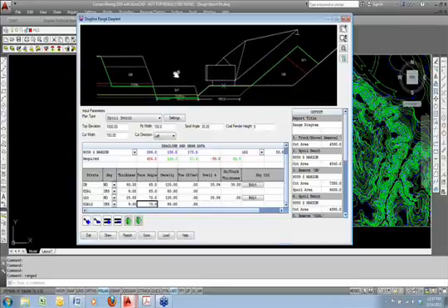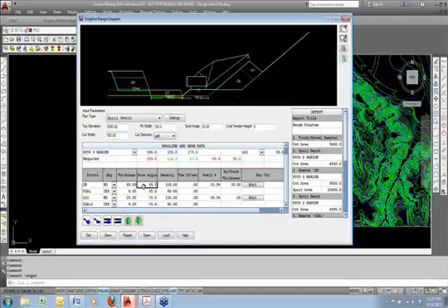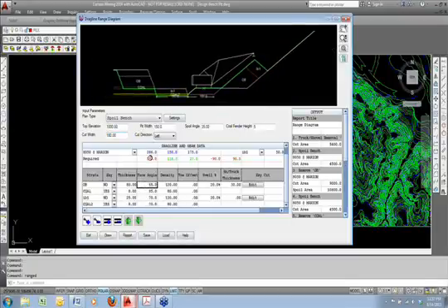So the use for this would be sizing your pit width. Let's say I want to change it. Maybe I want to try 180 on my pit width. And you concentrate on these color-coded numbers. The blue numbers are fixed. That's your dragline range. The required, if it's red, that tells you it's out of range. I'm at a full 90-degree swing angle, and I need 519 feet of reach to get over here. So that's not going to happen.